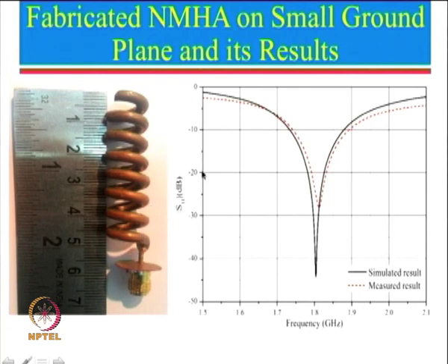So had it been a normal dipole antenna, it would be a figure of 8 like this, and the cross polar in case of the dipole antenna is very small, but in this case the cross polar component is not small. It is almost as high as close to 20 dB instead of 40 dB, which is practically realized by a dipole antenna.